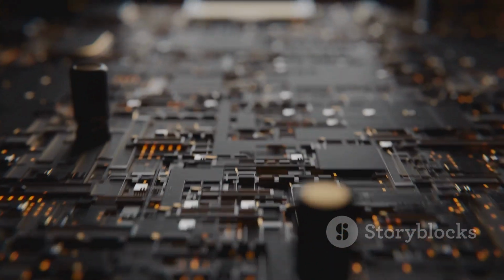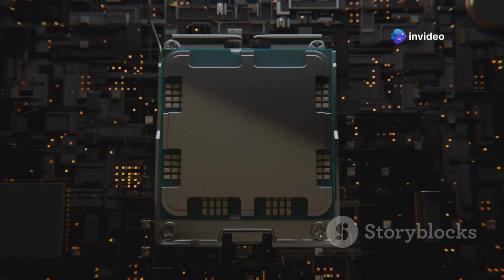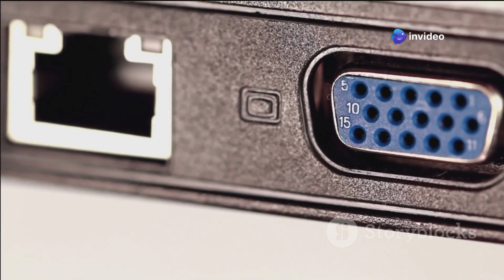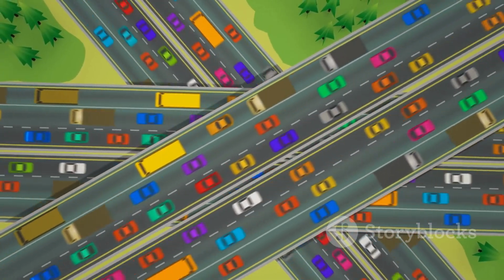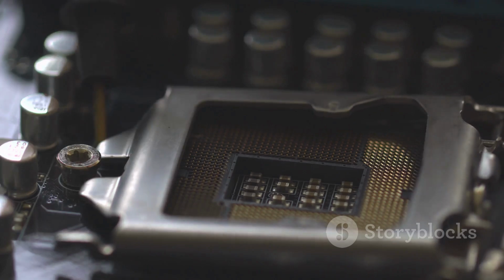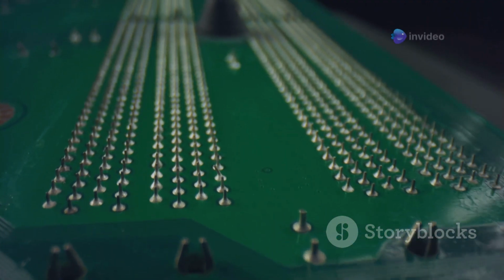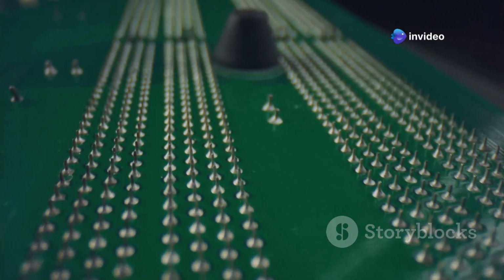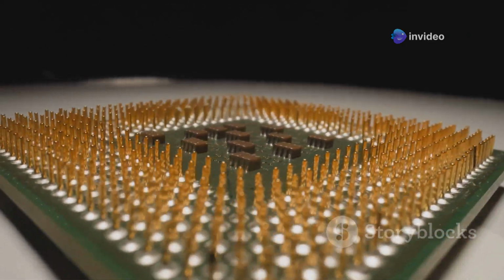This means it can access up to 65,536 different memory locations. Pins A0 to A15, multiplexed with the data bus, form this address bus. The data bus is like a highway. It carries the actual data between the microprocessor and other devices. The 8085 has an 8-bit data bus, pins AD0 to AD7. It can handle 8 bits of data at a time.